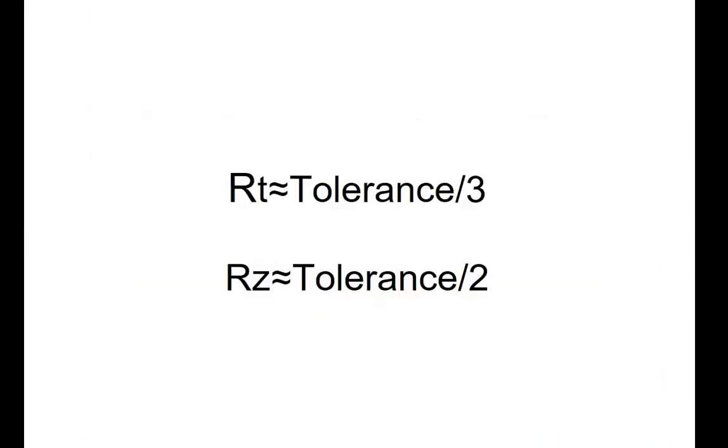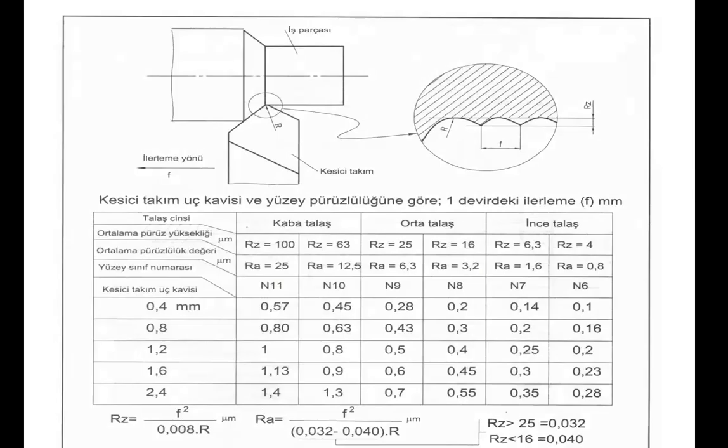And then the last part is to say that there is a relationship between the displacement speed of the cutting tool, okay, and the roughness value. F, lowercase f, is the lead of the cutting tool.